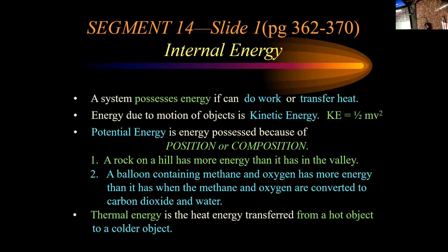Do the calculation if you want to. Your car's got probably about a 180 degree Fahrenheit thermostat in it. So you can convert that to Celsius, and then you can convert that to Kelvin. So that's going to be your high temperature for your car. And then the low temperature is the air temperature. Say you're driving at 80 degree outside temperature. Put those together and calculate the efficiency of your car. You'll find it's extremely low.